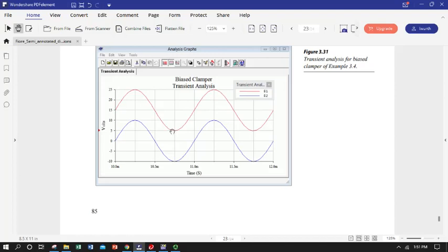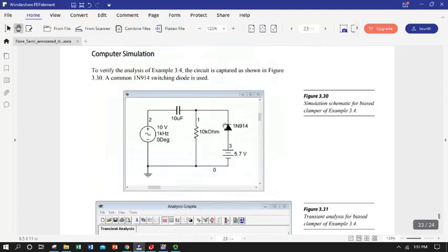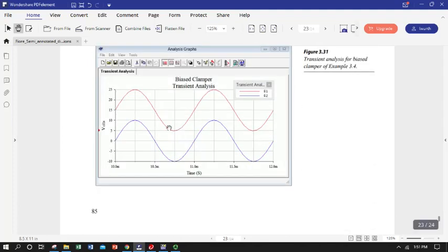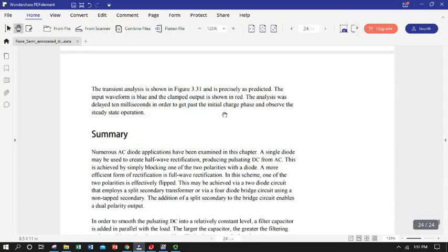Its negative peak has been clamped to the 5 volt minus the offset, excuse me, minus the forward bias voltage. Getting tongue-tied. So with clamping, the thing to remember is the action is going to be taken on the peak, not on the midpoint, the way it necessarily would if we had an inline voltage source.